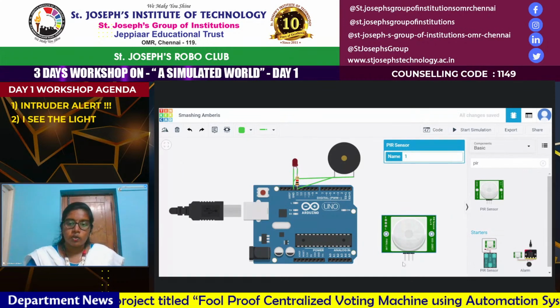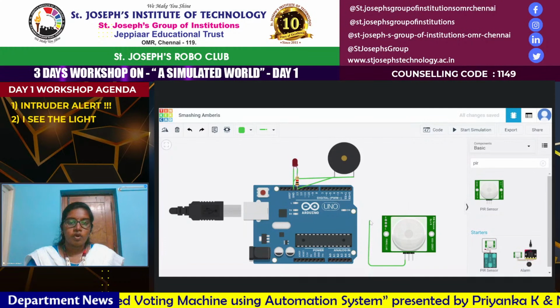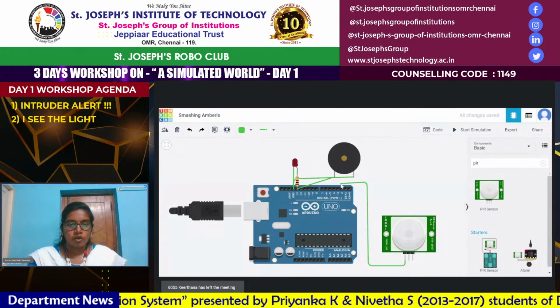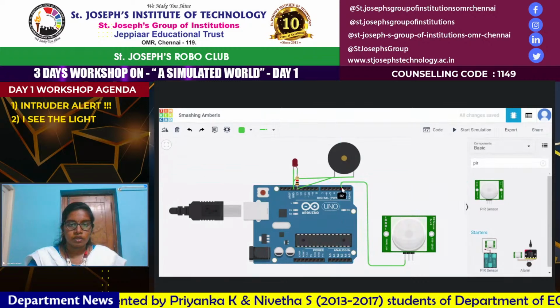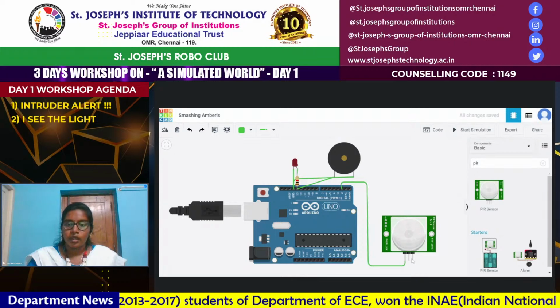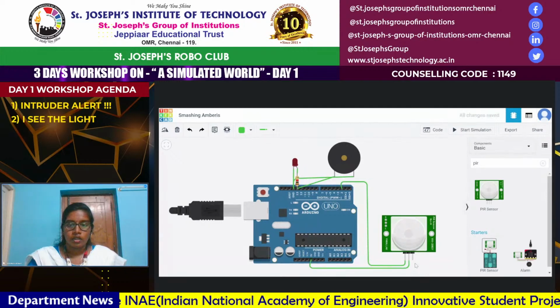Yes. So we have the signal pin here. I connect the signal to any one of the digital pins I want here, other than pin number 13. So let me go for pin number 2. I'm connecting the signal pin to pin number 2 here. And now the power to the 5-volt pin and the ground pin to the ground here again.